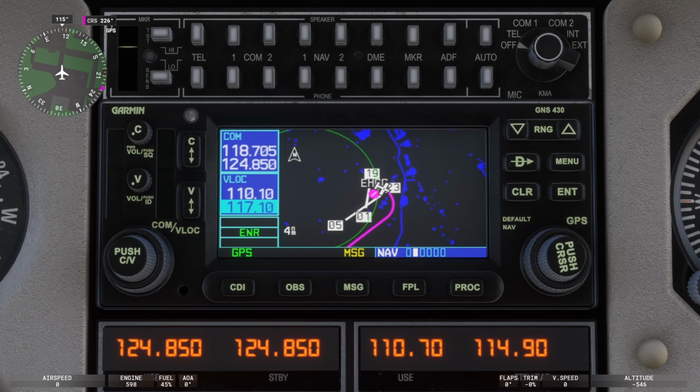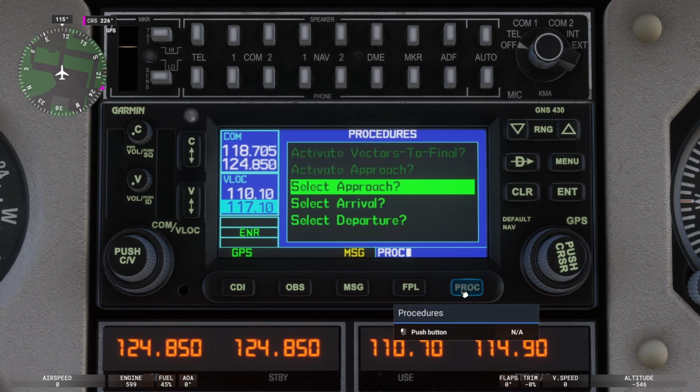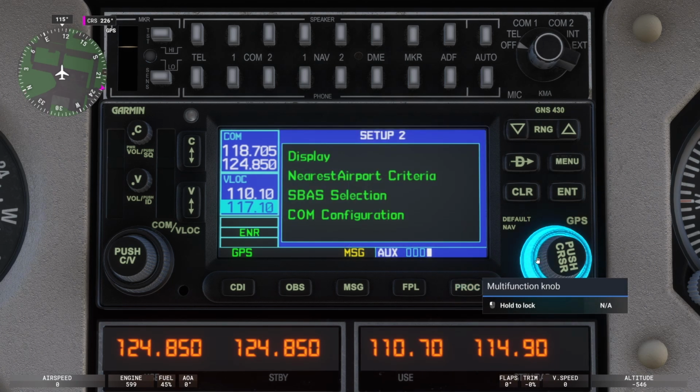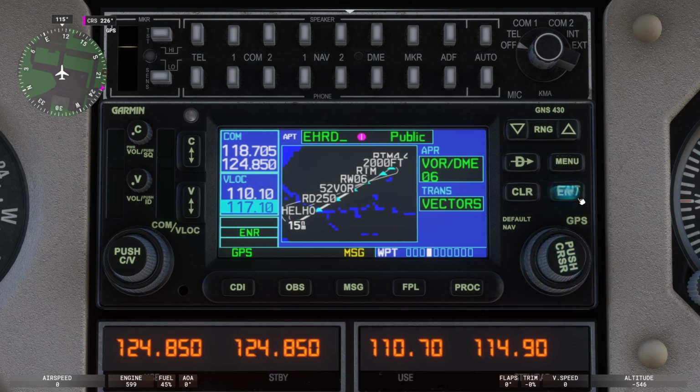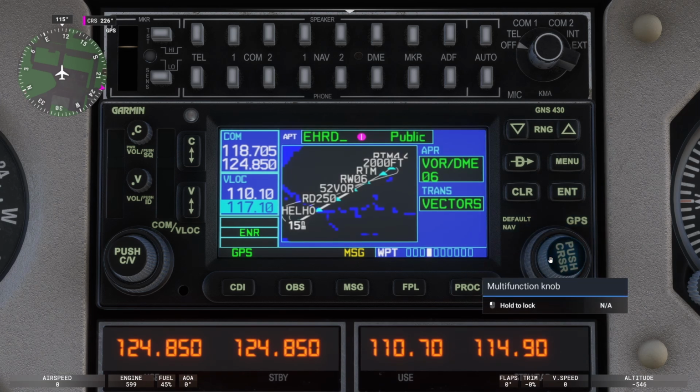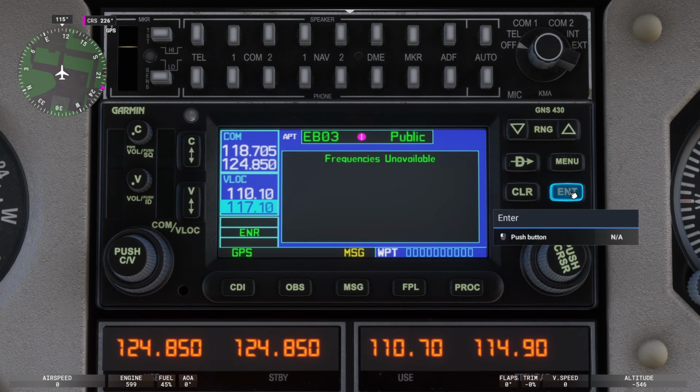While explaining that, I found another fix, and it's really simple. Even if you're seeing that error, ignore it. Press the PROC button, and it now shows the vertical approach. Let me show it quickly to you. To fix it, I pressed the enter button, and the enter button simply wipes out the value which we initially had over here. So I pressed the enter button, completely forgot this value, and took the destination airport.